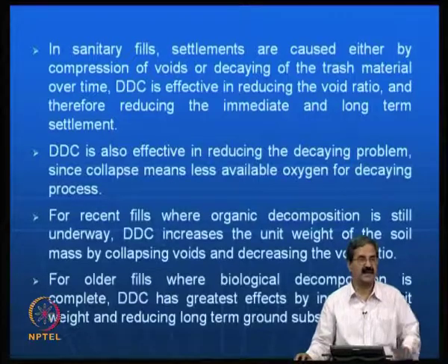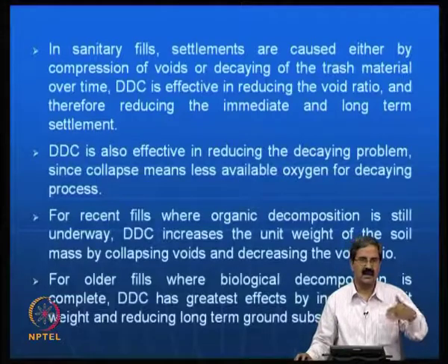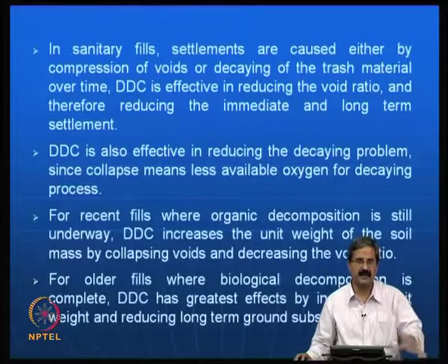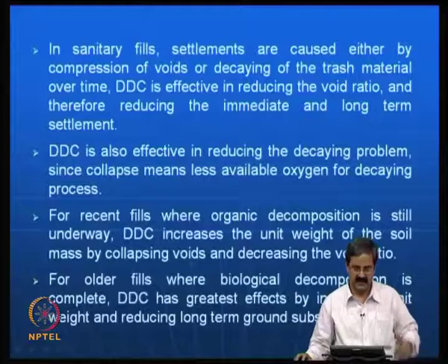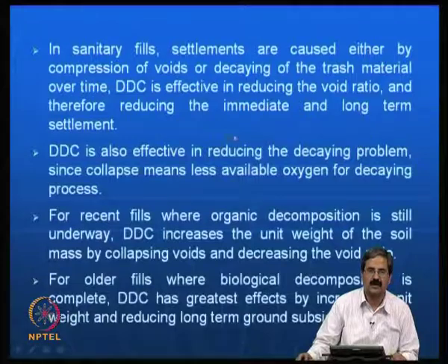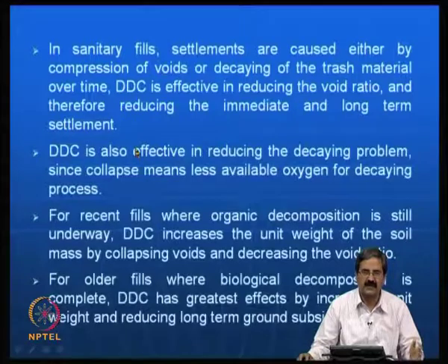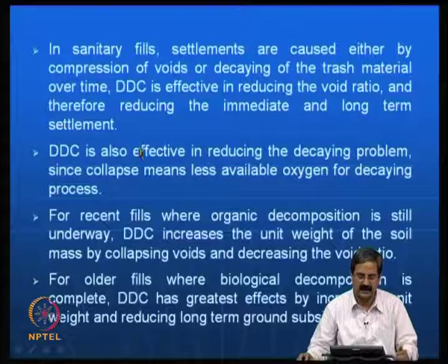As long as the materials are biodegradable, you have volume change. That volume change needs to be preempted, in the sense that if you compact it, definitely that much you are already able to compact it, so the post settlements will be much less. That is what is meant here, that dynamic compaction is very effective in reducing the void ratio, both in the immediate and long term settlement. If I have a waste dump somewhere and I use dynamic compaction, the immediate settlements are mobilized and the long term settlements will also be less.